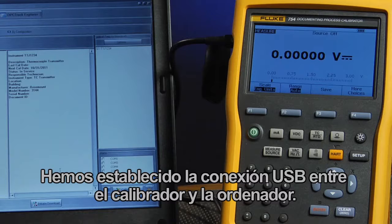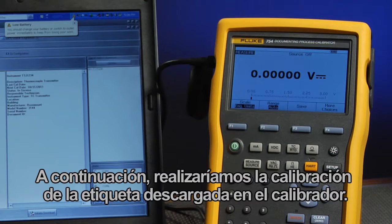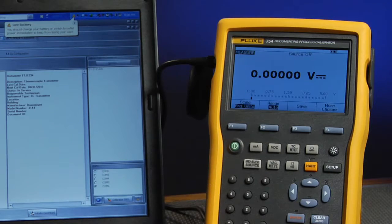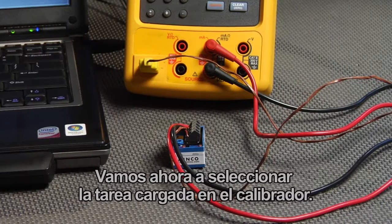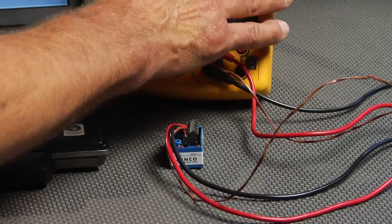We've made the USB connection between the calibrator and the laptop. Now we're going to initiate the download of the procedure into the calibrator. Now we would perform the calibration of the tag that we've downloaded into the calibrator. Next, we're going to select the task loaded into the calibrator. The task is configured for a Type K thermocouple transmitter.